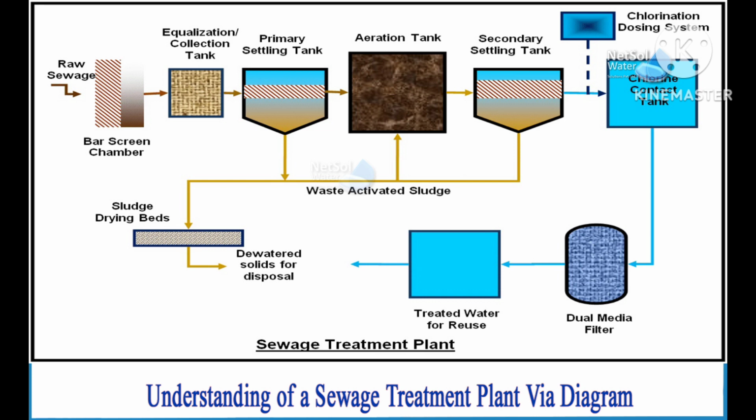After that, stage 7, water analysis and testing. The performance of the plant depends on testing for the right pH level, ammonia, nitrate, phosphates, dissolved oxygen, and residual chlorine level to comply with the NPDES permits. And the final stage is effluent disposal.